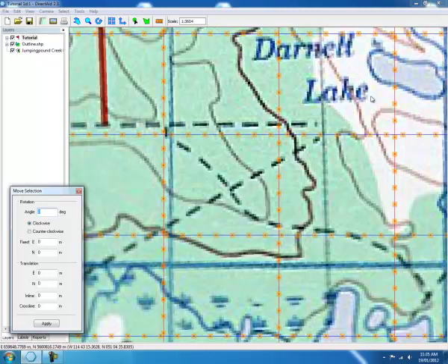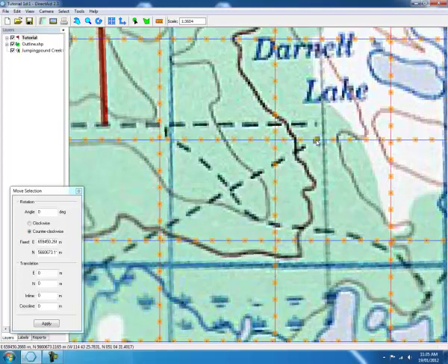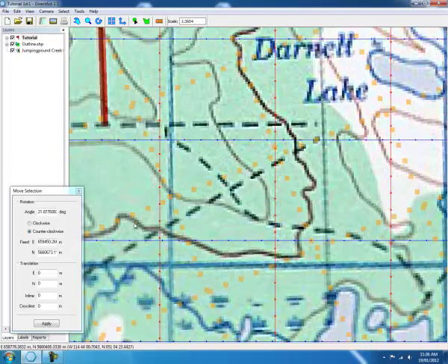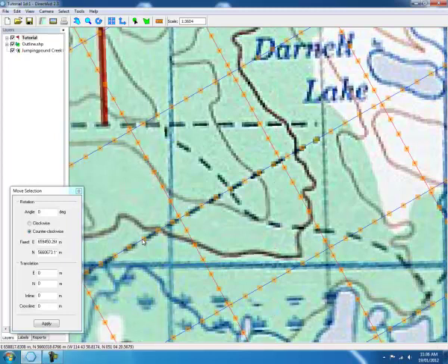First, zoom in and move one receiver onto an existing trail. Next, choose a second receiver on the same line, not too close to the first one. Hold the Shift key, then click and drag the second station onto the same existing trail. When you're done, you can release the Shift key. The receiver line should now be lined up approximately with the existing trail.